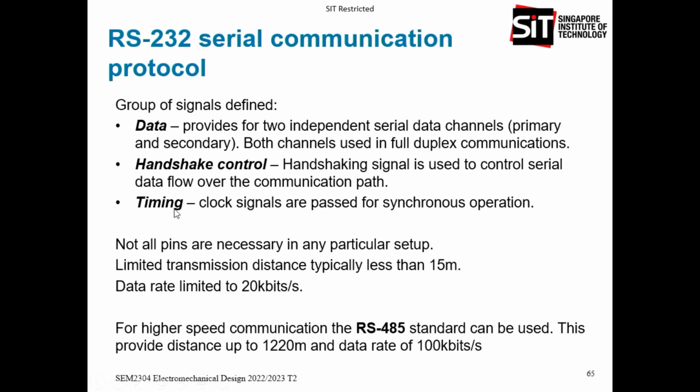First of all, RS-232. This one has been around for many years. In the RS-232, we have data line, and then we have handshaking control. We also have timing. UART and RS-232 are the slowest communication. For RS-232, you'll find that there are altogether something like 20 over pins that are defined, but not all of them are used.